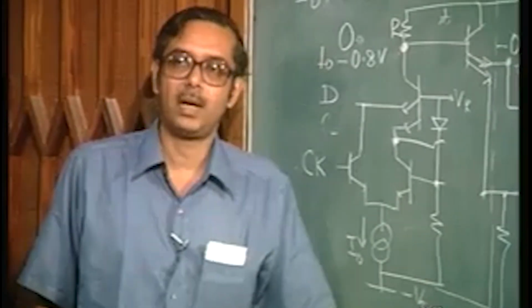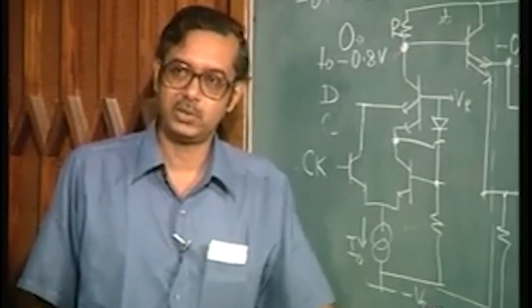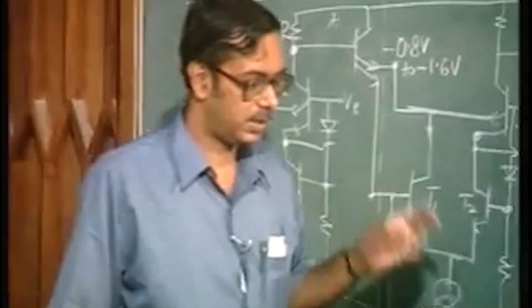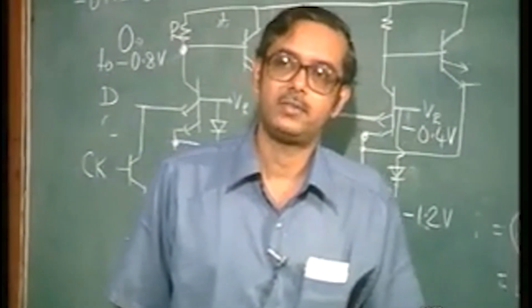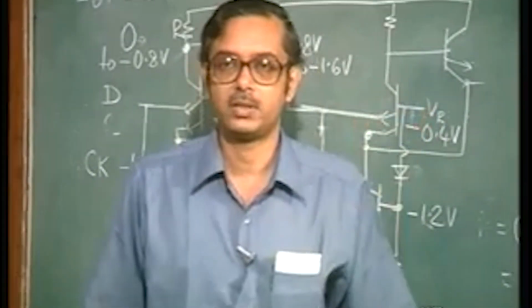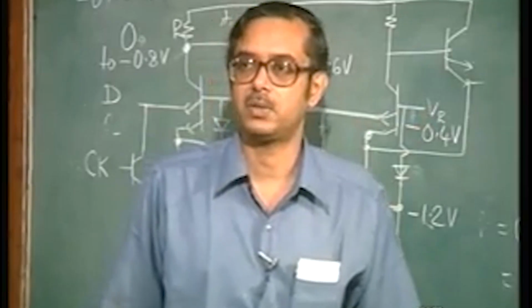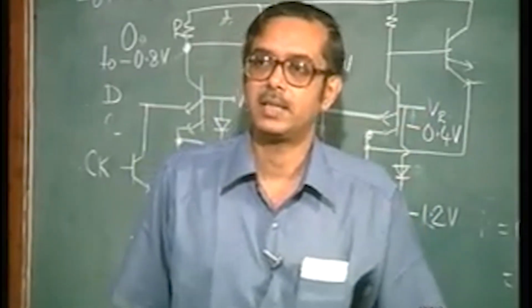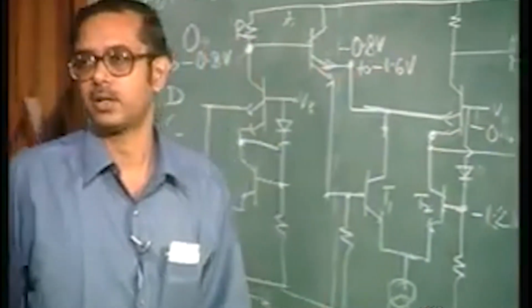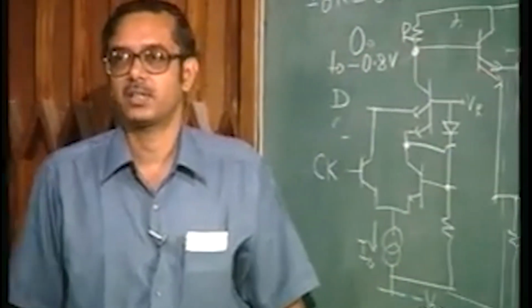See, if you reduce the power supply voltage, you automatically reduce power dissipation, and in today's world there has also been a drive to have lower and lower power dissipation, also because maybe you want a lot of handheld equipment which can operate with standard battery cells and so on and so forth. Maybe 1.5 volts people are talking of. All circuits should work with that voltage.